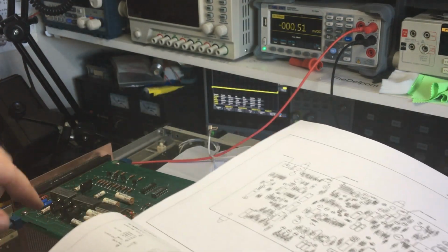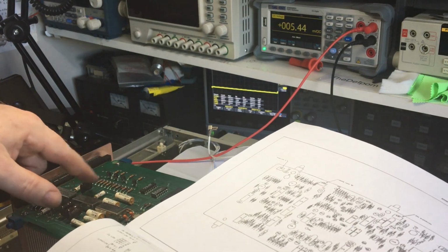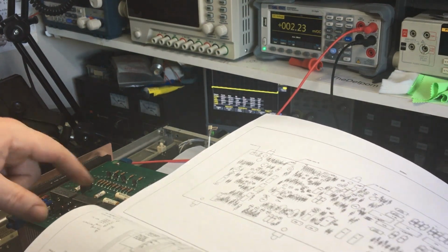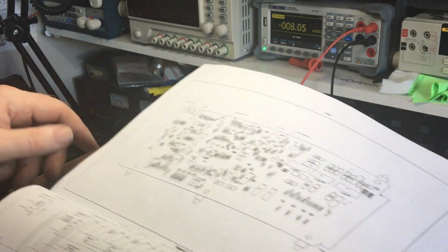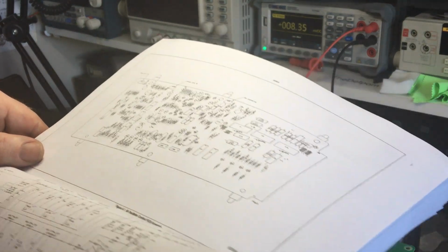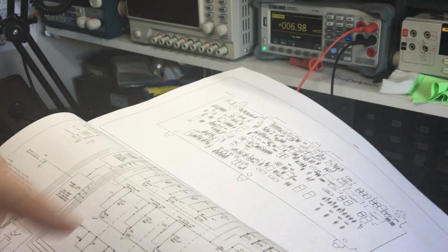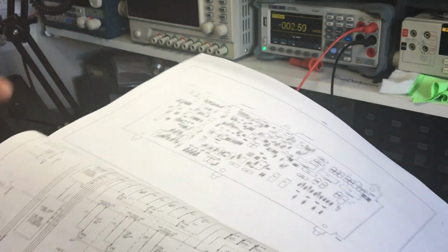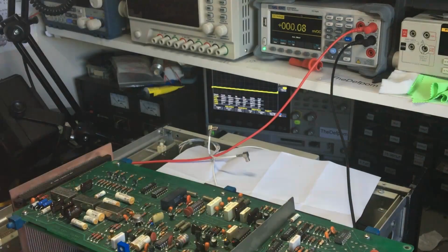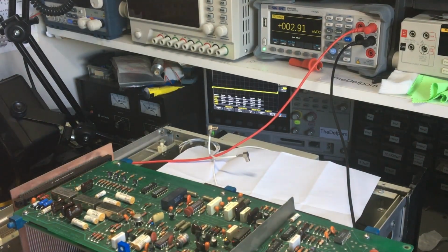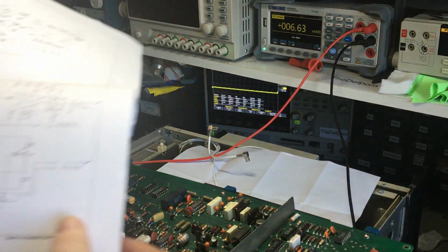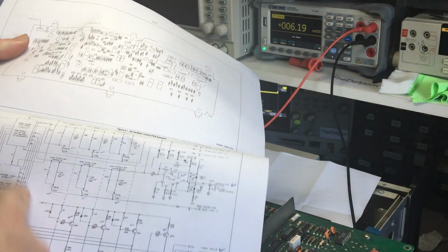What had been changed was around here somewhere. I think this one here might have been changed, which is C52, but then it's an optional thing, it's not necessarily required. And C52 is used on the 1 kilohertz range, and that seemed fine, so I don't think there's an issue there. It's probably just factory tuning. So far so good. No faults found yet. It's a process of elimination, so I believe this is probably okay.